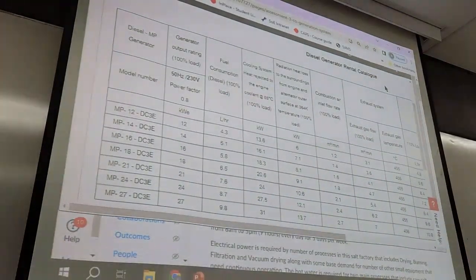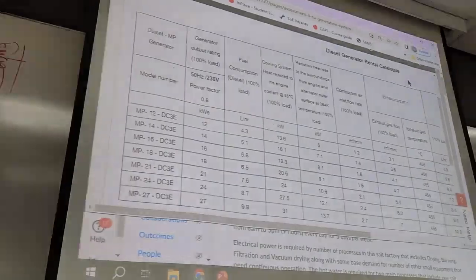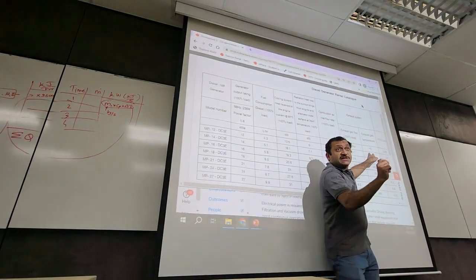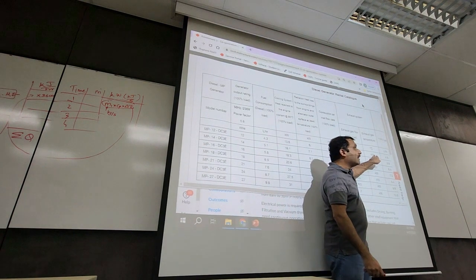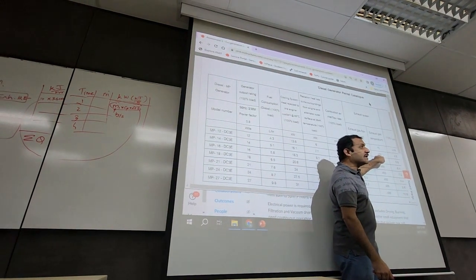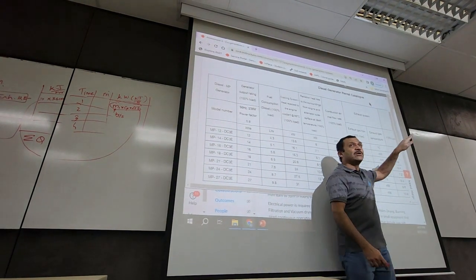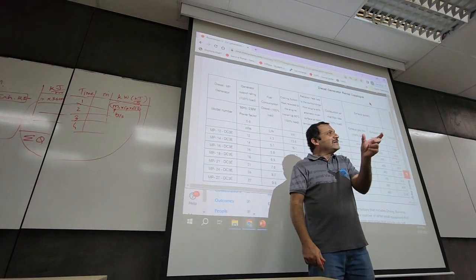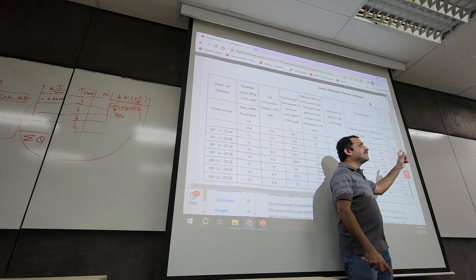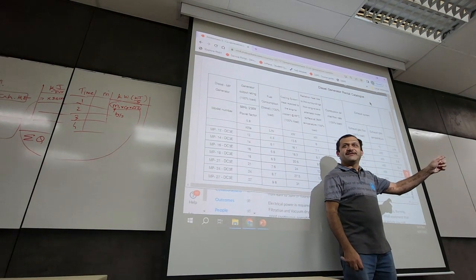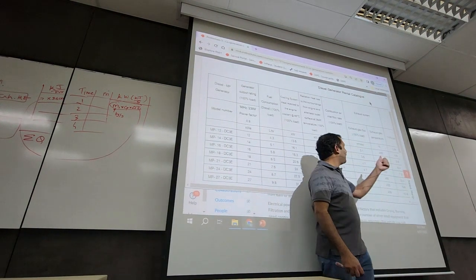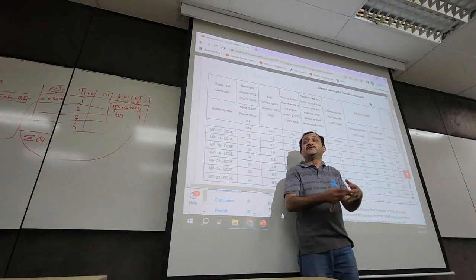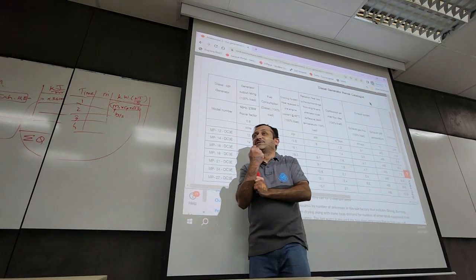So as an engineer, you will put in a control system. You're going to control the temperature. Even in the theory, when you calculate, you're going to say we're going to cool down that exhaust from 455 to only 110. That's the lowest we can do. So delta T is 455 minus 110. Delta T multiplied by the mass flow rate of the exhaust times Cp of exhaust gives you the amount of thermal energy in the exhaust.